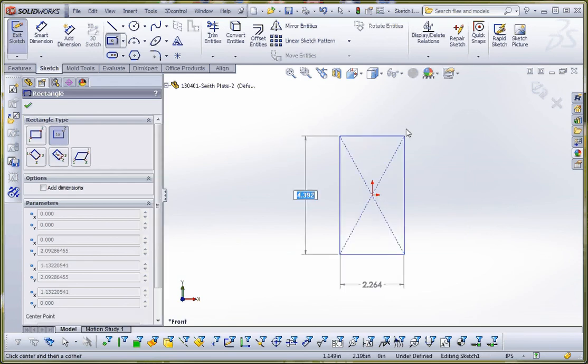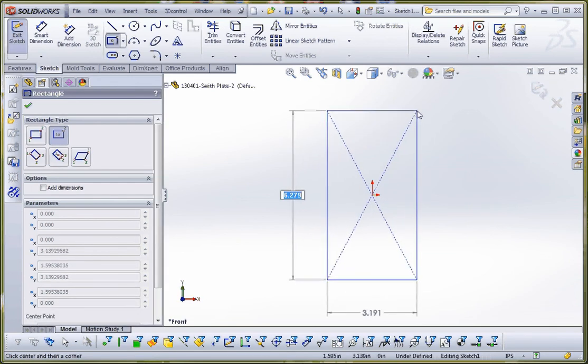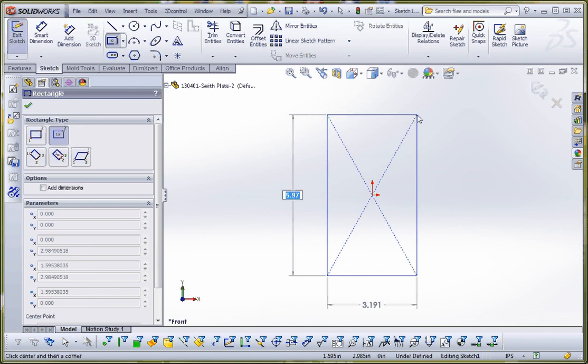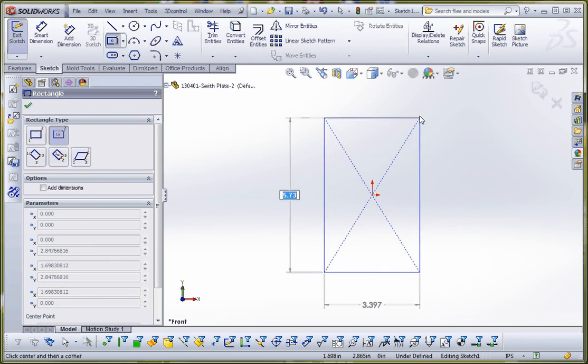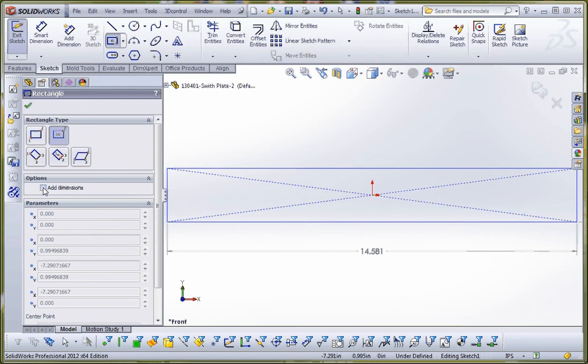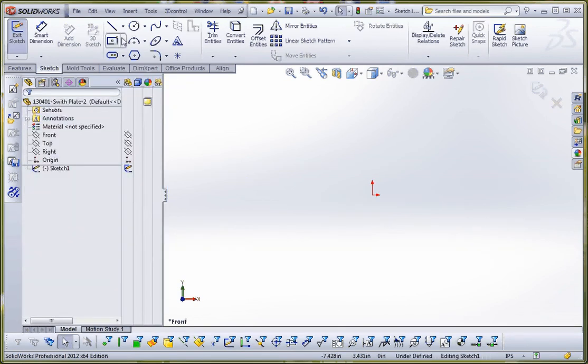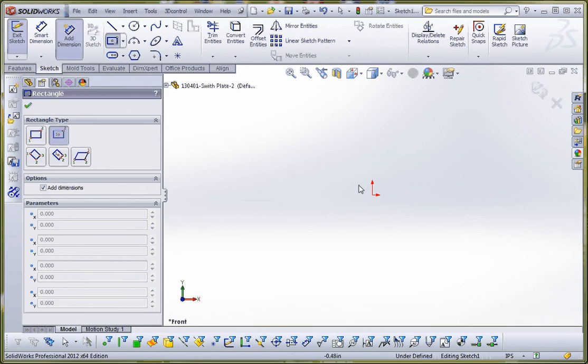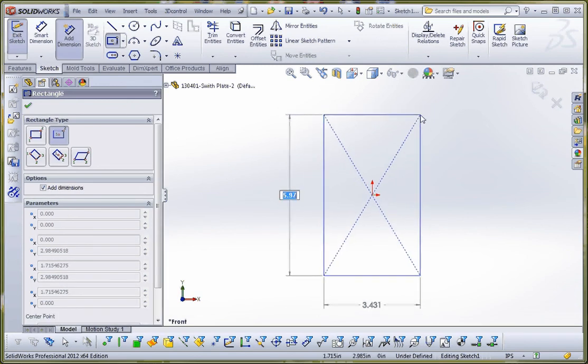Normally you would go in the middle here and extrude it out. You see some dimensions out there that are associated with it. They're grayscale in the background, which means they're not going to be automatically added, but we could click on this over here and have it actually add dimensions for us. So let's try that again before we actually place it. We could have it add those dimensions for us. It'll put those in there.